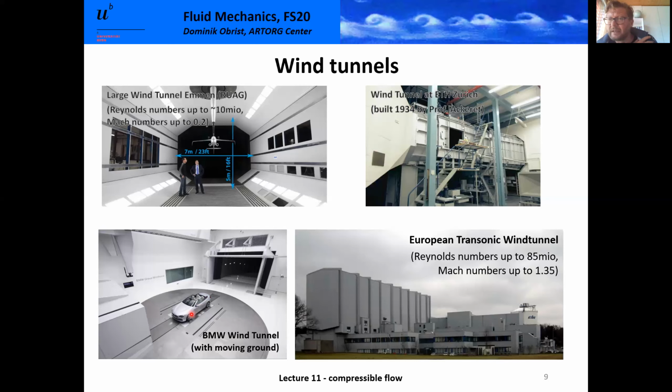Now, if you happen to have just a non-moving solid wall down here and the car sitting on top of it, and you have air passing through, then locally, this will look like a channel with 2 solid walls, and you will develop a Poiseuille flow going in the gap between the car and your floor, right? But that's not really what's happening in reality on the road.